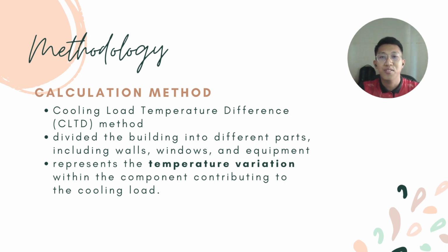Now let's proceed to the methodology we use for this project. To calculate the cooling load of buildings, we apply the widely used and straightforward cooling load temperature difference, or CLTD, method. This method utilizes the temperature difference between indoor and outdoor conditions to estimate the cooling load.